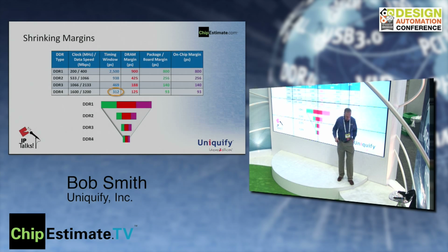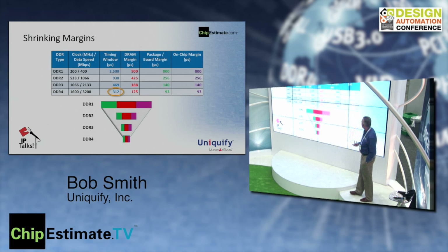So the reason this is critical to DDR is there's very little timing margin to play with. By the time we get to DDR4, our allowable timing margin is down to around 300 picoseconds, meaning that when your design is done, you better be within that 300 picosecond window across every condition you could think of, whether the product is out in the desert, or buried under the ice somewhere. The point is, maybe you're making 1 million of them, so you better make sure that it works with all the other parts that it's connected to.